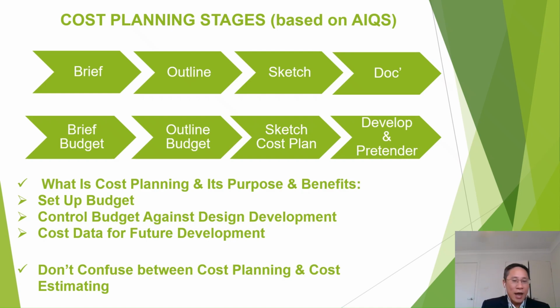And another example I would highlight is that for tenders, some contractors don't even do the takeoff for quantities and cost estimation during the tender. They just use their cost data based on cost per square meter and submit tenders for lump sum contracts.